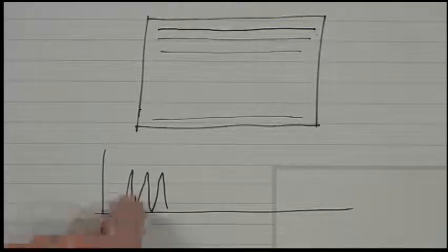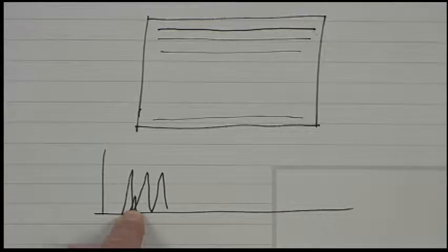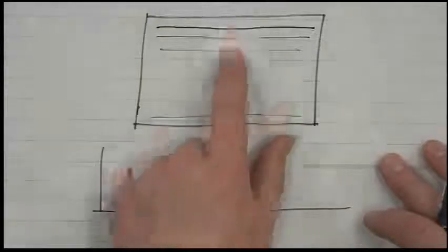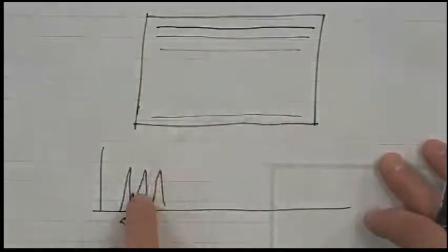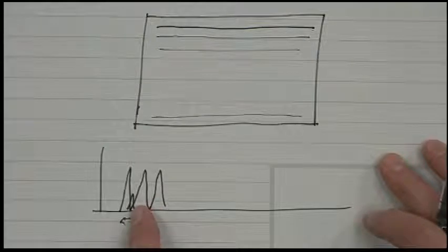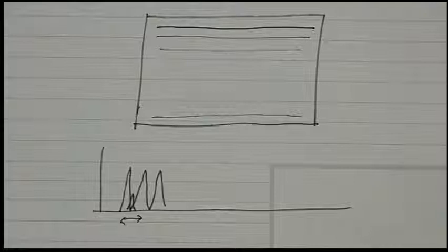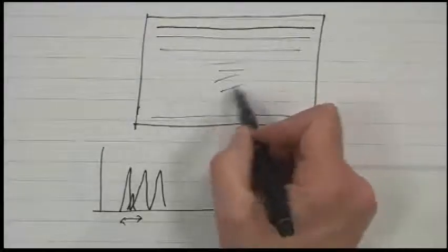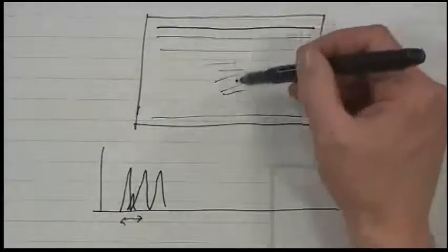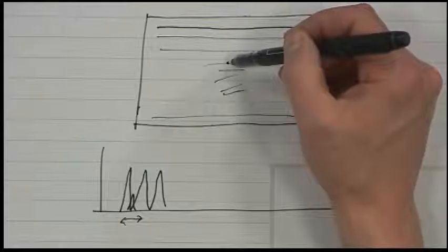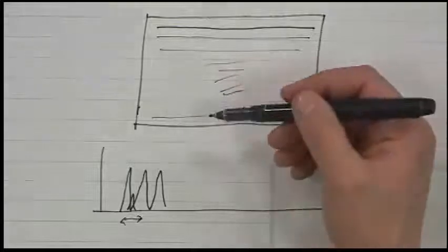The comb filter would do a better job of separating the color and the black and white out. But what would really happen is that if there was a lot of high-frequency content in the vertical direction here, then it would screw up this comb structure, and some of the gray achromatic signal would get into the color. And then you'd have crosstalk between the color and the black and white. And what would typically happen is if you had a lot of high-frequency content here, you would get rainbow effects because the monochrome, the Y channel, the achromatic channel would bleed into the channel, and you'd get artifacts.